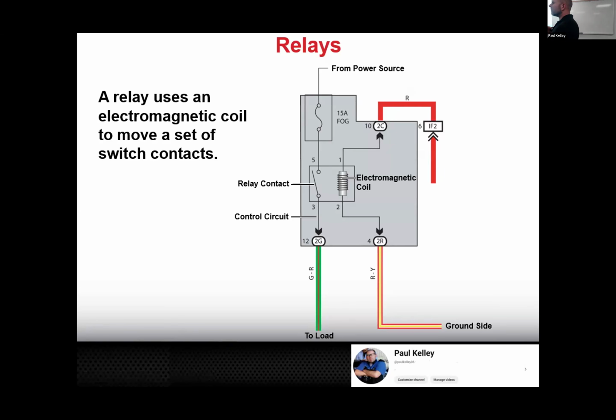So I'm giving you the fundamentals of how the relay works, but to get a real complete understanding, you've got to know how to read a wiring diagram. So if I wanted to test terminal 1, I can't. It's inside the box. I would need to test terminal number 10, which is in the connector like we were talking before. Terminal 10 may come in like this, and you actually have to locate number 10. What color do you think that's going to be?